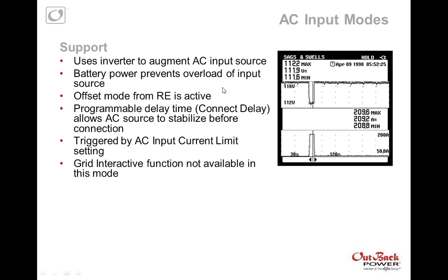So for example, let's say we're running 30 amps of load demand on our critical load center, and we're limited to 40 amps input, either by what the generator can do or the circuit breaker protection. And we get this 40 amp load demand in our critical load center.